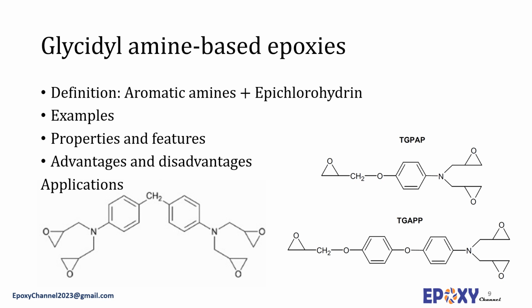Compared with the epoxy resins of diphenyl propane, glycidyl ester epoxy resin has a lower viscosity and better workability. High reaction activity. The adhesive force is higher than that of general epoxy resins, and the cured product has good mechanical properties, good electrical insulation, good weather resistance, excellent ultra-low temperature resistance, and a still higher bond strength than other types of epoxy resins under ultra-low temperature conditions. It has a good surface gloss, light